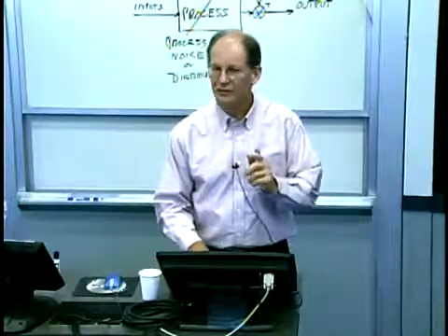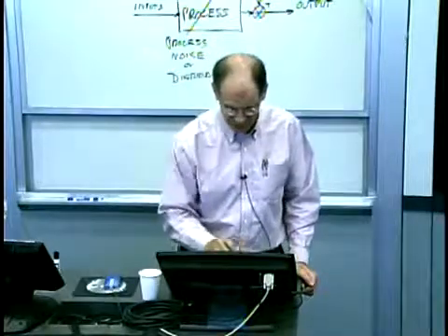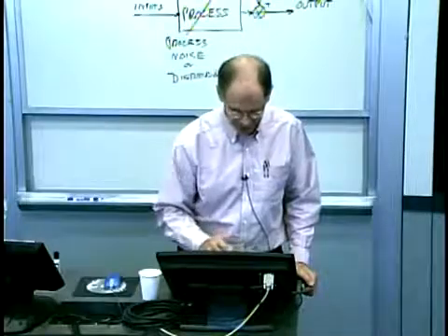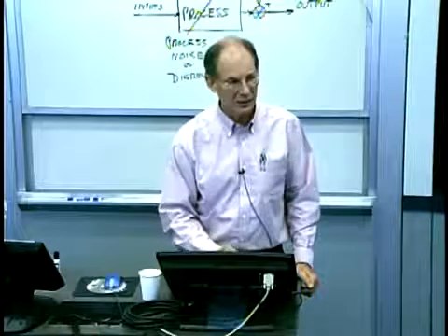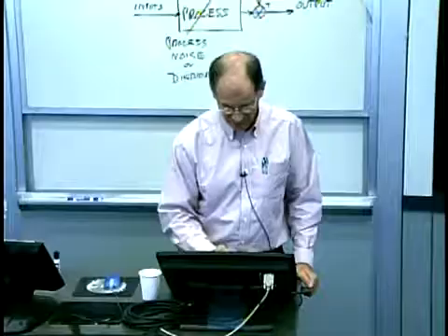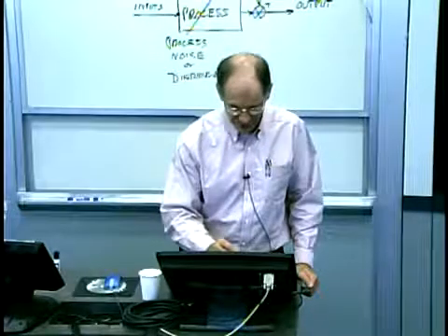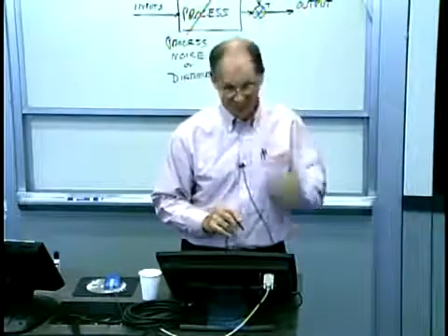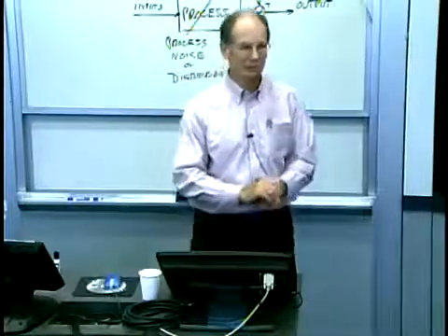But here's the challenge if you're actually applying SPC. How do I look at data in real time and distinguish the difference among something that looks like this? This is actually a mean shift here. Now that I look at something that looks like this, which is exactly what I wanted to see, something where you've got a mean shift, something like this where I've got a mean shift and standard deviation shift, and something like this where I've just changed the whole probability distribution.